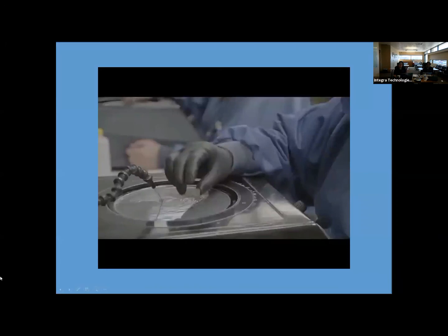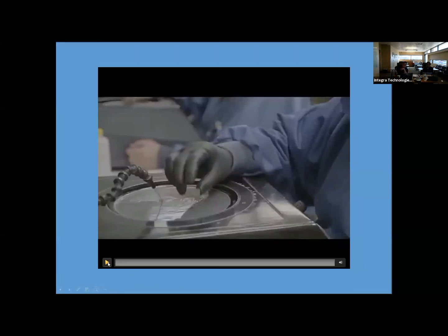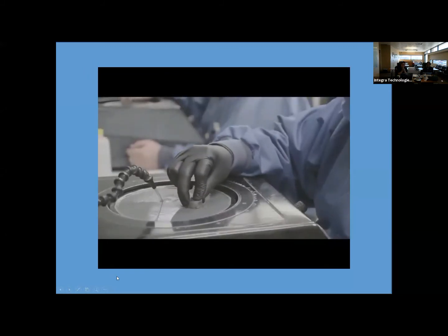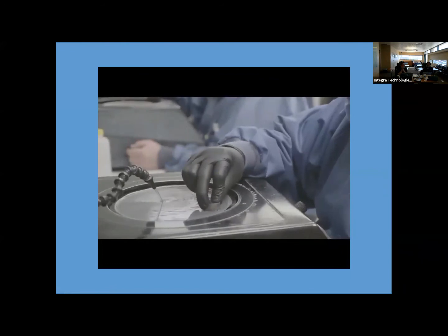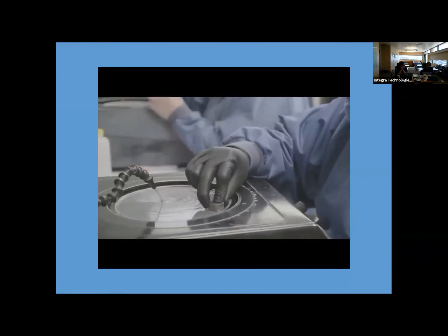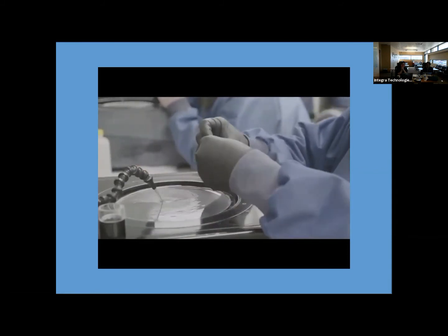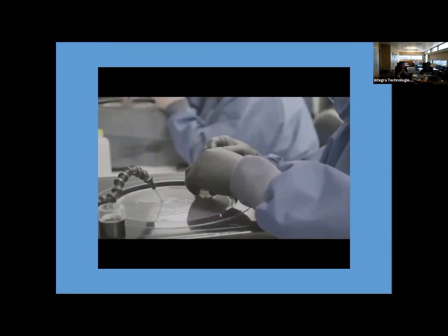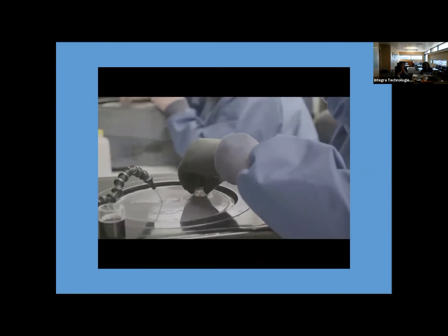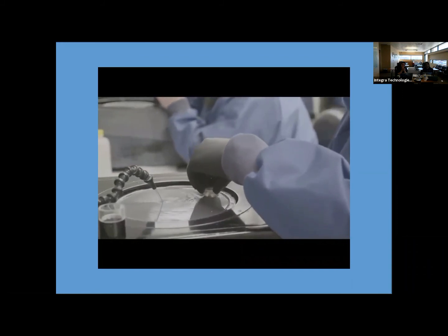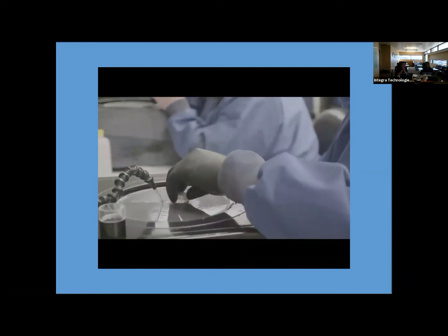So I think I've covered all that testing. Lo is going to show a video now of cross-sectioning in process. Here we call it rocking the turntables because you have a cross-section, and as you can see, the technician is grinding into that part until the area of interest is achieved. So basically the part is embedded into a glass material, if that's what you're going to call it. An epoxy, yeah, an epoxy.